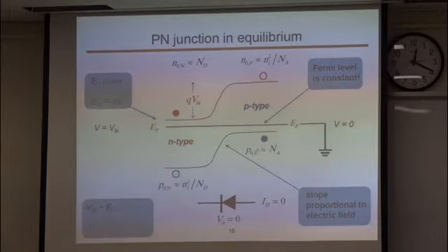On the other hand, holes will be diffused from P-type to the N-type because the concentration of the holes will be higher in P-type than the N-type. And this diffusion will generate positive charge in N-type in the place of the original electrons. Can you understand this part? Okay, let me draw it here.